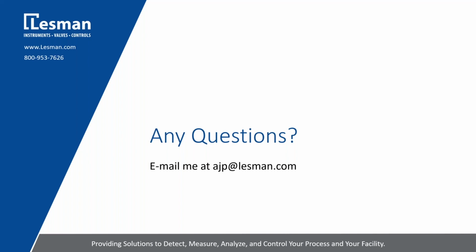Hi. But basically, I think what you just covered was what I was concerned about: atmospheric conditions, of course, on the makeup air when it comes to conditioning of the incoming air. It is typically cooler or even higher moisture content. And what I've got is a fire eye system, flame rod, and it will just be sometimes frustrating because I need it to burn off, but the fire eye wants to go into a lockout.